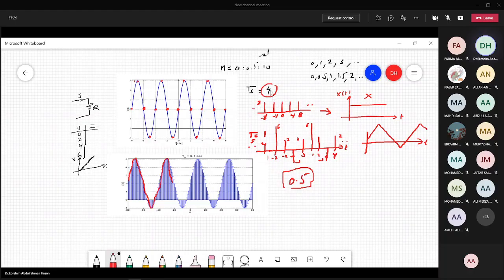So TS is the problem. If you are taking a very high TS, it means you are losing data, so it won't give you the real shape, the correct data. And if you are taking a very small one then you need lots of memory. Imagine someone says the best is to take a 0.000001 step.